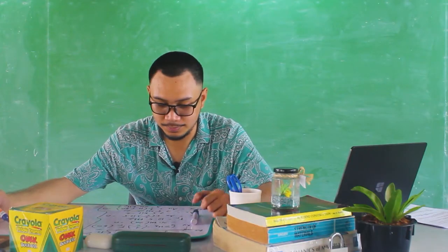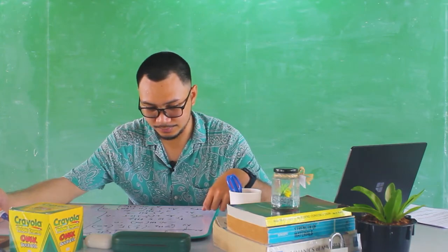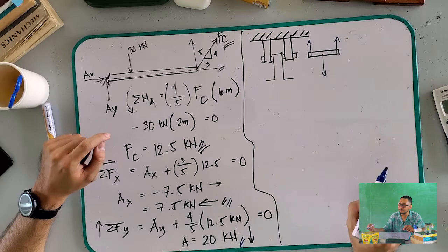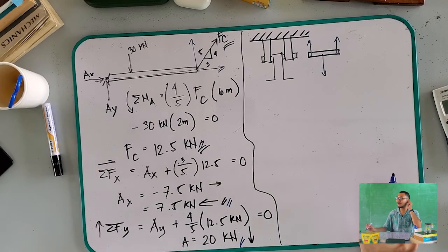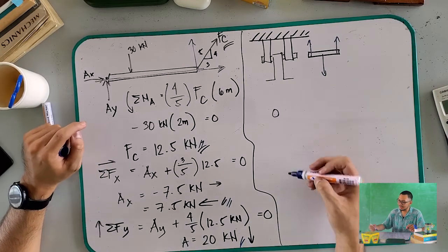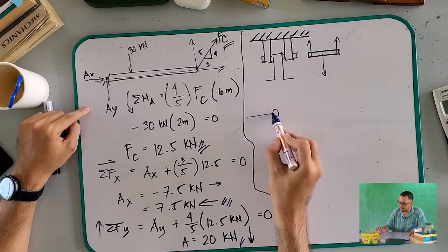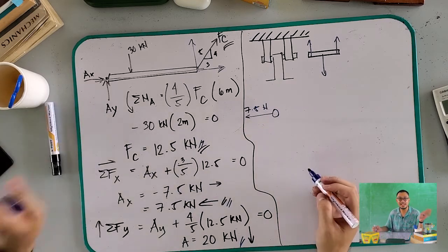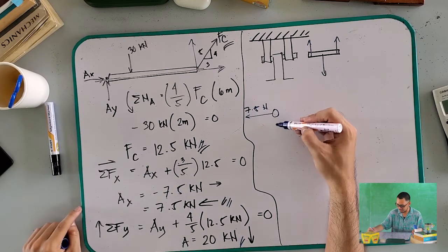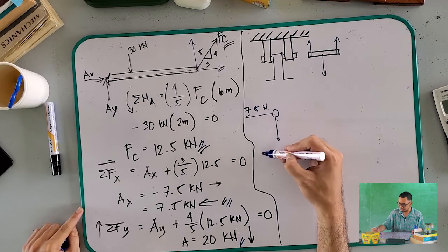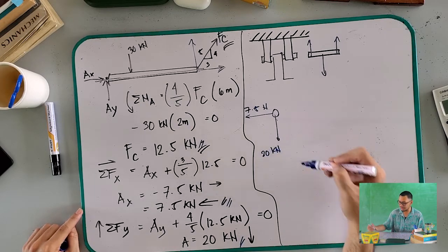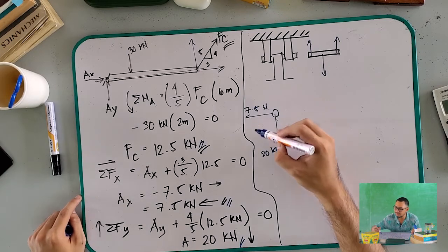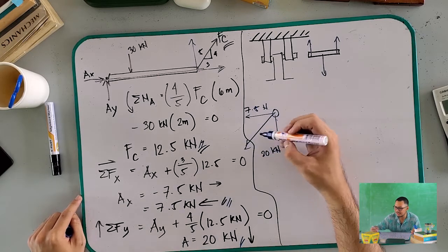these three. And what is the direction? We will not mind the direction, but that is the reaction on our pin. Okay? If we look at the side view, our pin has a component of 7.5 kilonewtons to the left, and also a component of 20 kilonewtons downwards. Okay? So, therefore, the resultant is in that direction.